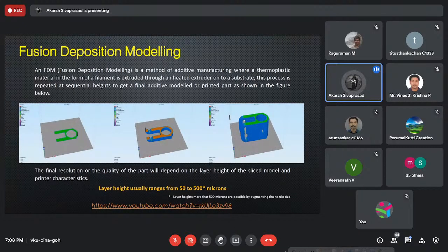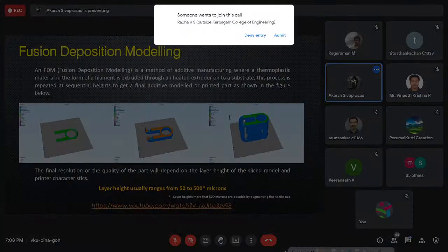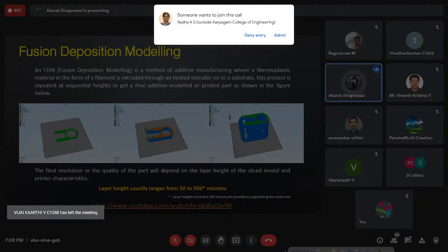The molten filament is deposited on that specific path, and once that layer is done, the z-axis stage moves down by the layer thickness, or whatever your slice thickness is, and then you do the next layer on top of the first layer. After your entire layer stack is completed, you end up getting a final object as in image 3, on the far right.